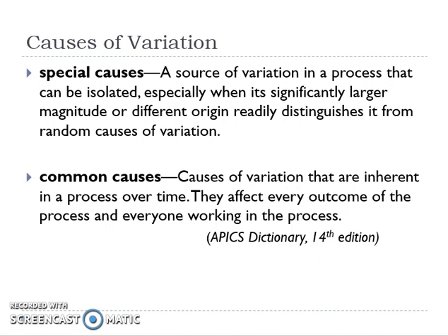And then common causes. These are variations that are inherent over time, like fatigue, wear and tear, temperature, things that are common. The goal is to eliminate special causes immediately, get to the root cause and get them out of there, and then mitigate common causes as much as possible.